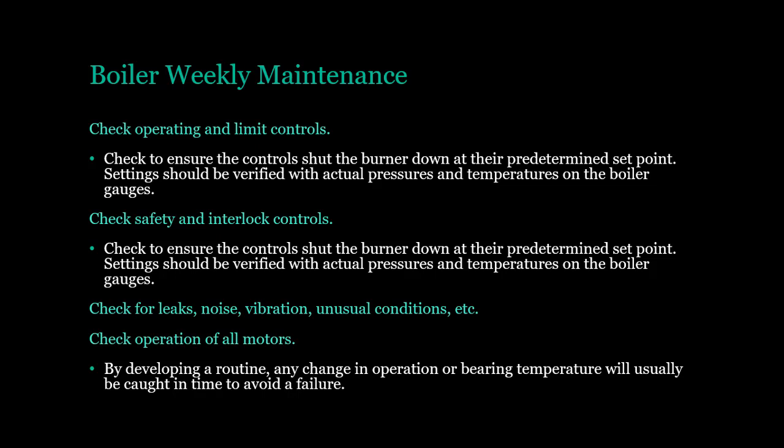Check safety and interlock controls. Check to ensure the controls shut the burner down at their predetermined set point. Settings should be verified with actual pressures and temperatures on the boiler gauges.